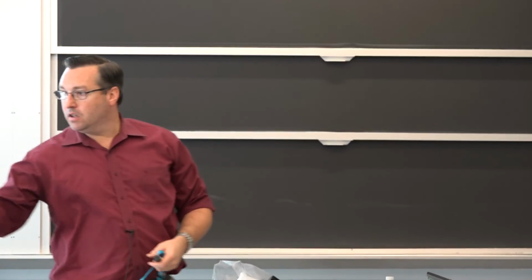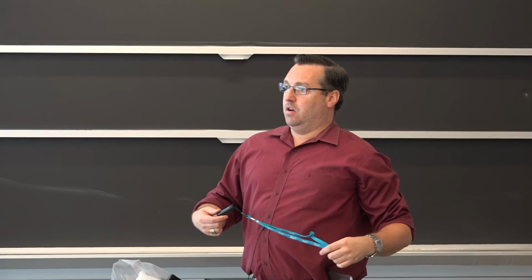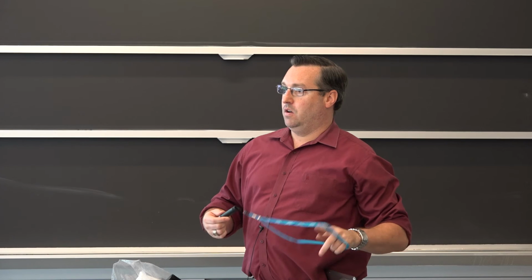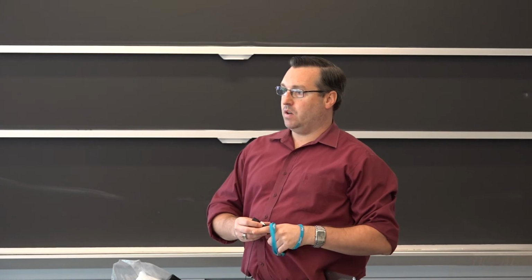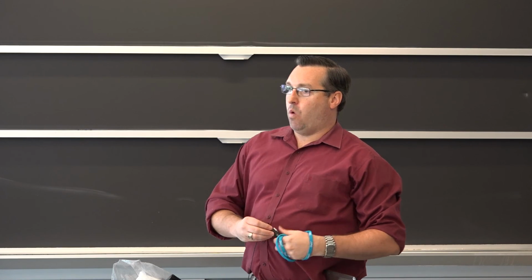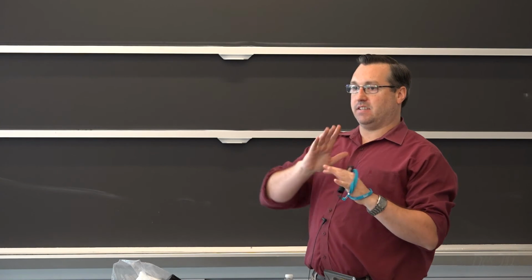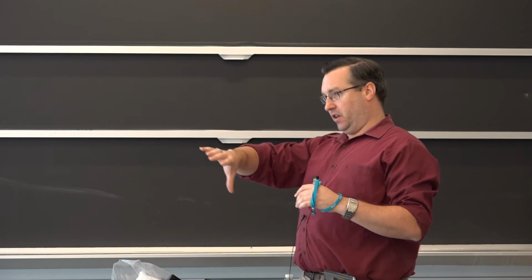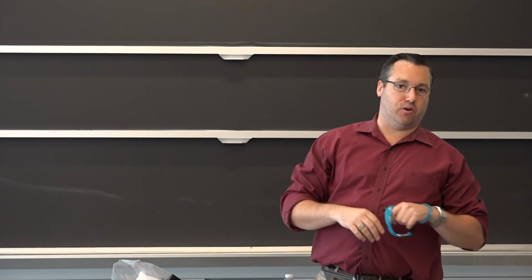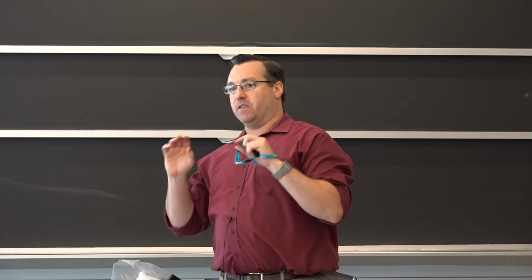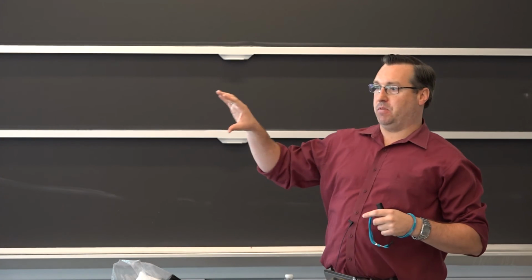For these types of tests, are there any standards about simulations you have to run on new materials, or is it mostly just we know the properties and we're going to replace it and then test it a bunch? Well, a lot of times you'll do the actual mechanical testing hand in hand with a computer simulation. The ASTM standard or API or whichever standard your material has to conform to will tell you minimum acceptable limits.